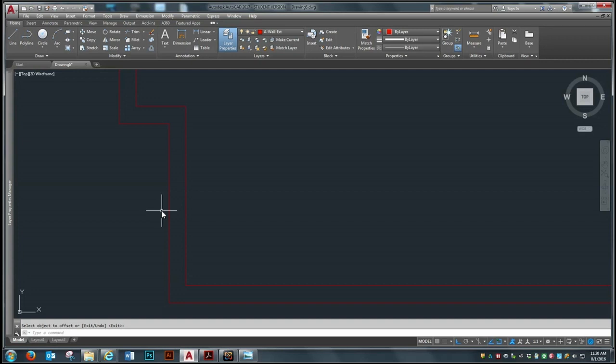So I like using 3 foot doors when it's possible. You know, sometimes a 3 foot door on a small closet doesn't work. All right, but all residential doors are 6'8" tall.